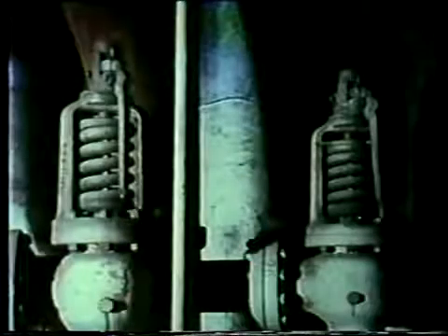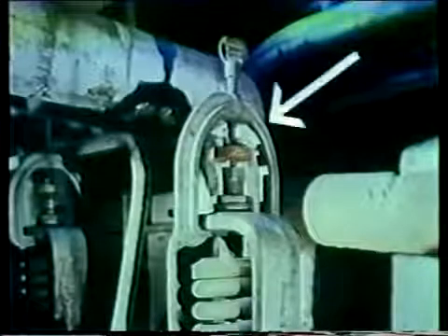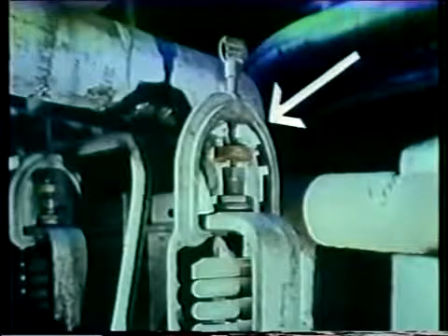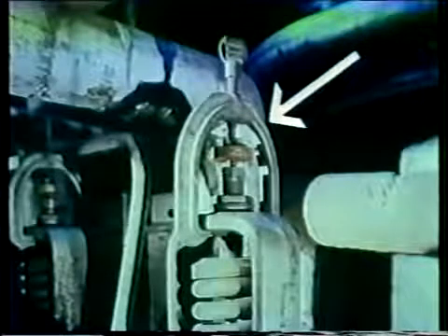Also, you should check the safety valves to make sure they are not gagged. The safety valves are sometimes gagged when performing a hydrostatic test. It's very important that these gags be removed before the equipment's put back in service. We talked about gagging earlier in the section, and it was in your text when we talked about hydrostatic testing.